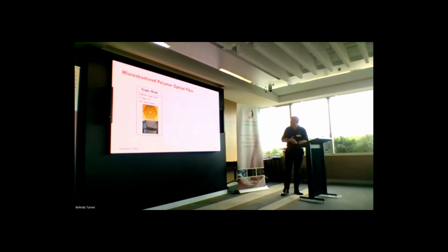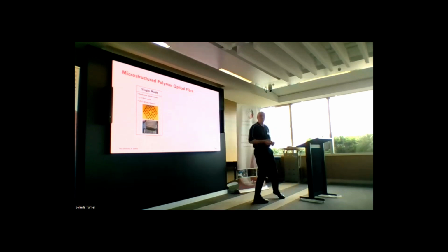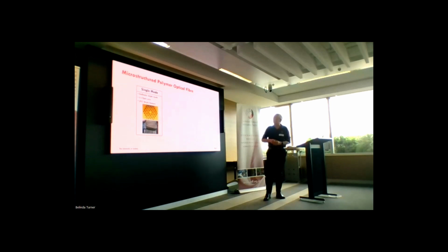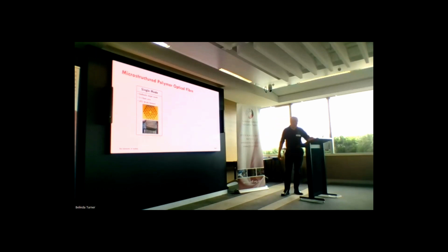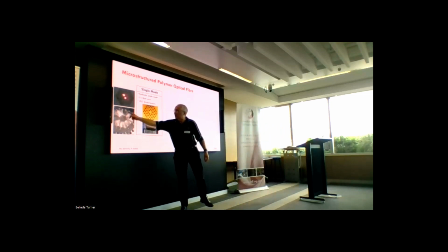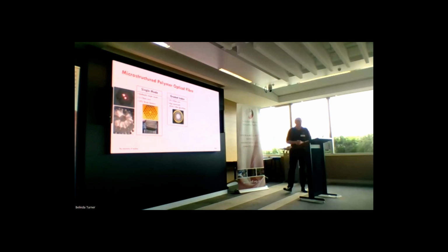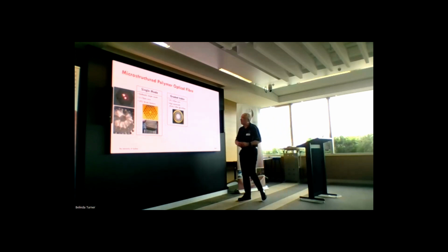So here are some examples. We made some single mode polymer microstructured fibre. Those regular arrays are very easy to get in stack and draw. You've probably seen those earlier. The interesting thing we could do with polymer is it's much easier to stretch it. So we made some long period grating strain sensors with this. We also have made twin core single mode fibre, and this is a double clad fibre with a single mode core in the middle and a large high NA multi-mode core around it. This one is really cute, graded refractive index multi-mode fibre.